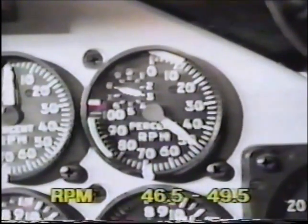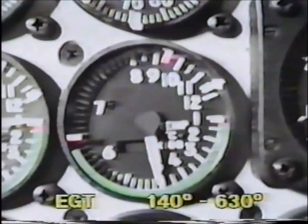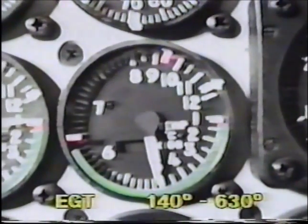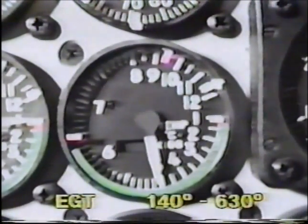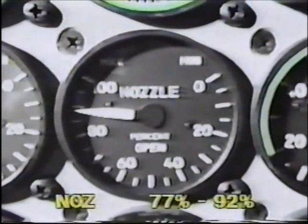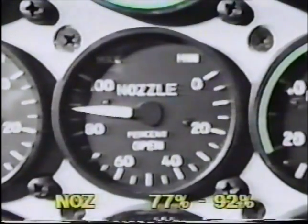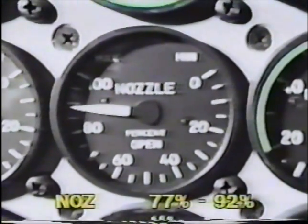The tachometer should indicate between 46.5 and 49.5. No limit is specified for idle EGT, but it must be within the continuous operating range of 140 to 630. The nozzle position indicator should read 77 to 92% open with no fluctuation.